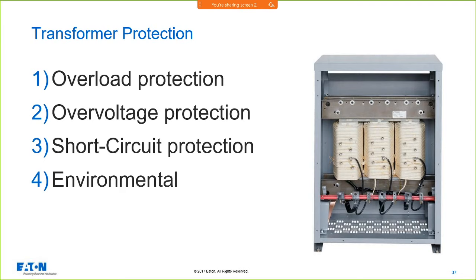Your over voltage protection, transient voltages, you've got to think about transient voltage surge suppression. And in some cases, you might apply snubbers. There's IEEE papers and whatnot, and there's snubbers that you can buy to help protect those windings. You've got to just make sure that this transformer can take what you throw at it, what the system throws at it, let alone what it can inflict on the system.